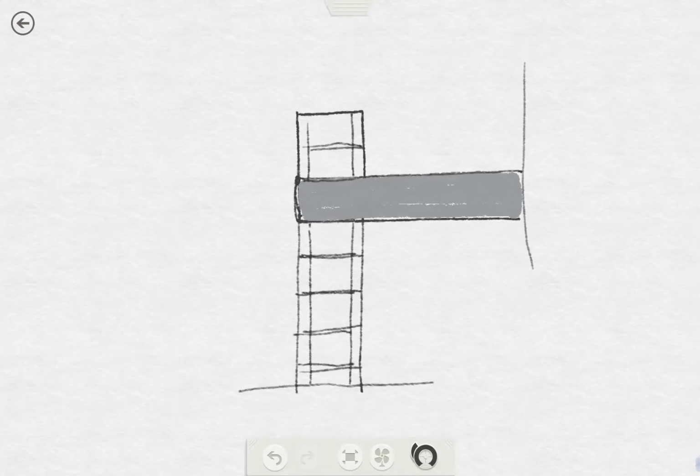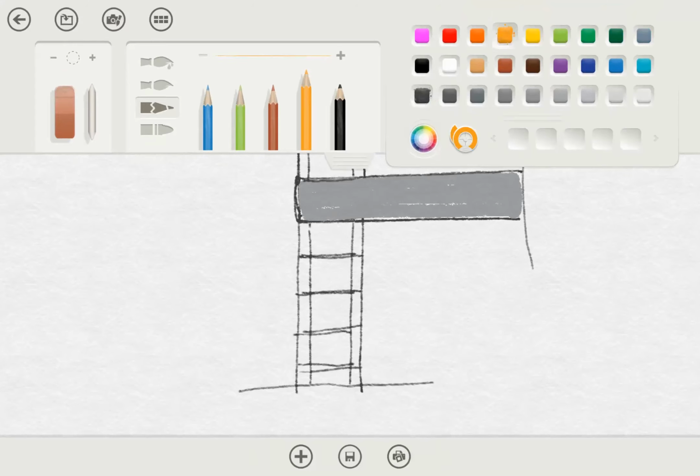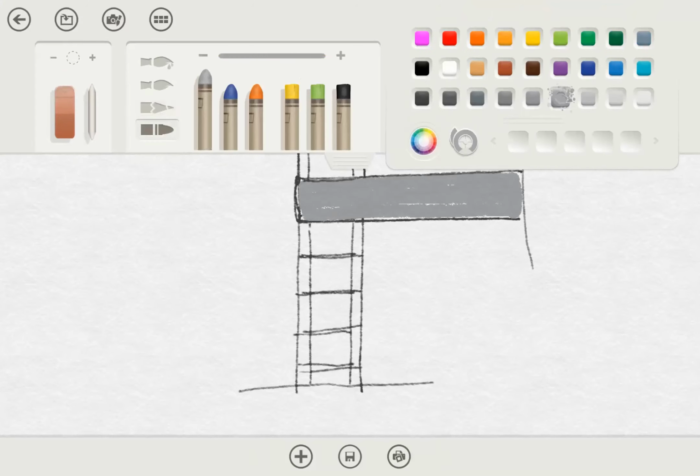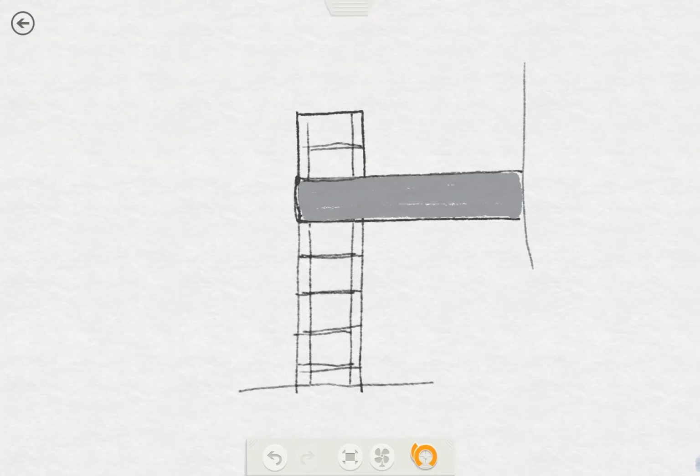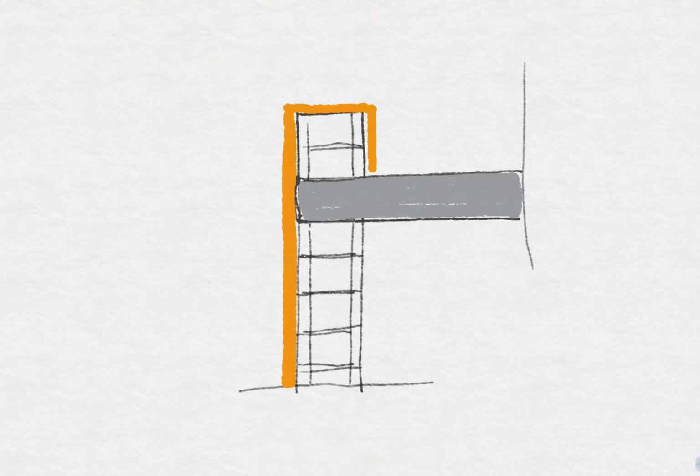The thermal insulation material works well when we wrap all this detail with thermal insulation. So if we have this orange or yellowish material, we have to wrap all this with thermal insulation, even the parapet.